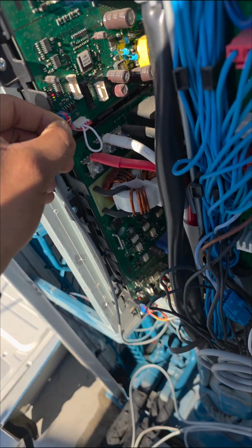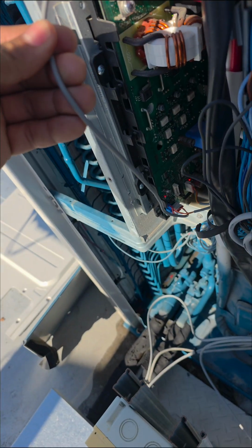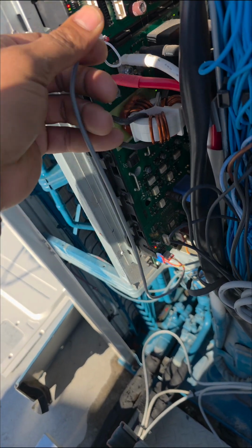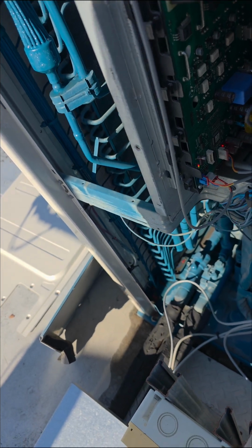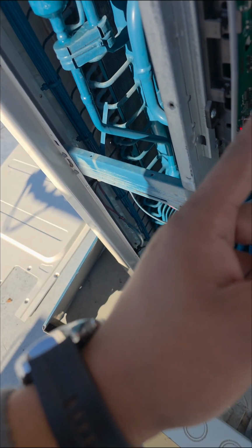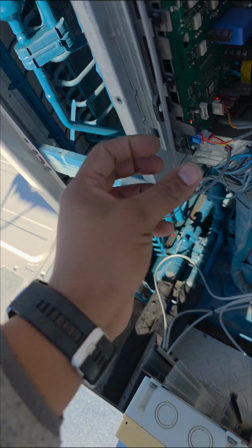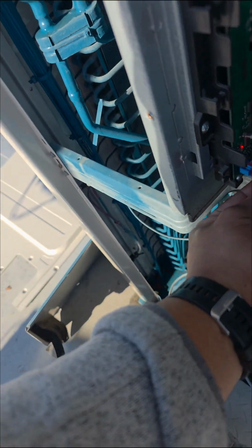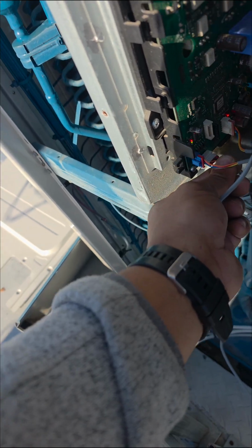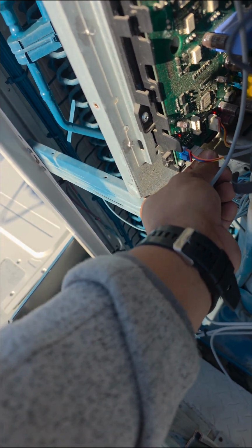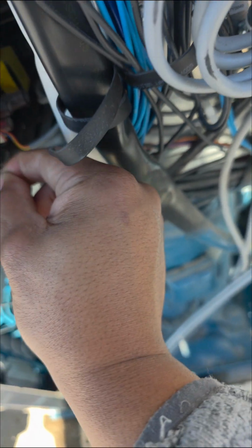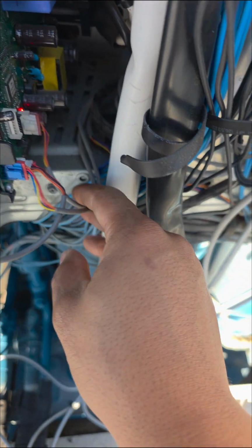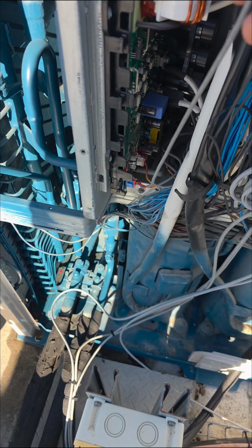But something is funky on this comms line. I think we need to investigate and see if we've got a damaged cable or if it's the board that's intermittently giving us issues. So I think I'm just gonna go ahead and remove this board. We can always do some bench testing to see whether or not this board is a problem, and then we could probably just have a look at this cable as well, just to make sure that there's no kinks or any damage on this cable.